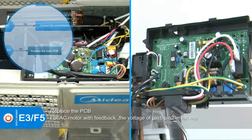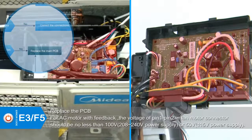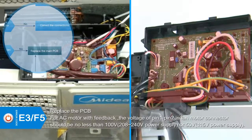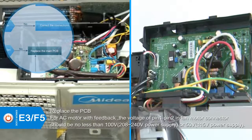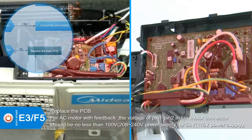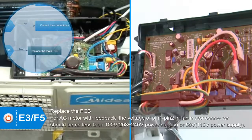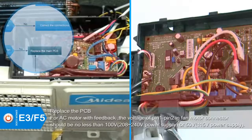Examination for main PCB board. AC motor with feedback. Turn the power on and set the unit as running in high-speed mode. 15 seconds later, measure the voltage of pin 1 to pin 2 in the fan motor connector. If the value of the voltage is lower than 100 volts for a 208 to 240 volts power supply, or 50 volts for a 115 volts power supply, the PCB must have problems and needs to be replaced.